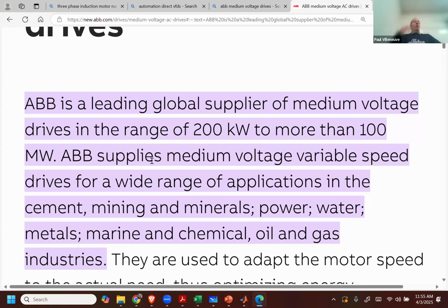So yeah, the joke was if you looked at old cars that had air conditioning and power this and that, you had serpentine belts that would go on all these different places because they got their power from the rotation. Now in modern cars, even the fan for the radiator is electrically driven. Why is it? Because what if it's not hot outside? You might not need to blow air on the radiator to cool it. So the car will monitor the temperature of the antifreeze and make a decision. Yeah, we get to blow air, we don't blow air. So it's a more efficient car. So just by changing a couple things from the old ways of everything had to be mechanical to making them electrical has resulted in massive improvement in fuel economy.